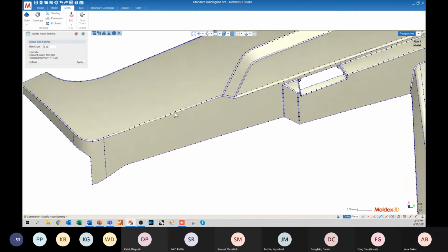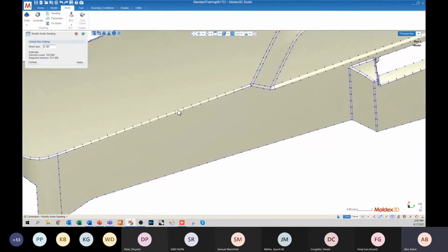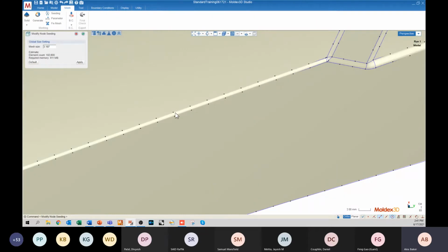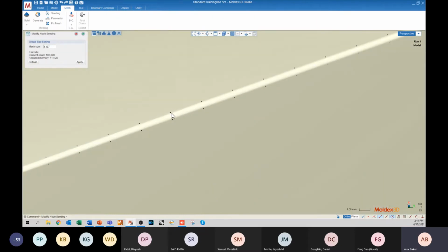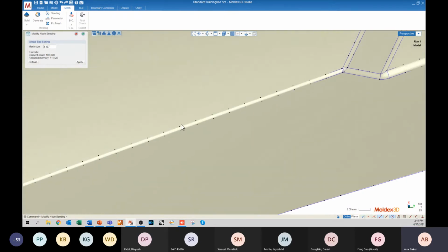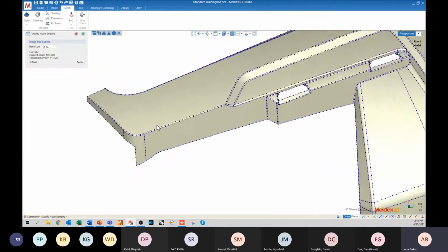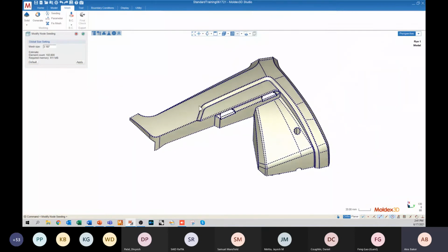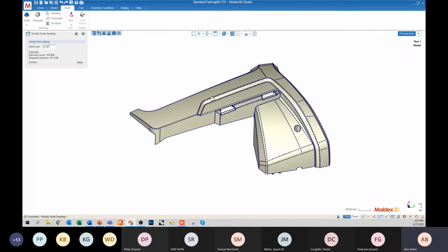All right, the spacing of these nodes dictates one side of the triangular element. So you could think of one element being this node and this node, right? So as I propagate that to the middle of my surface, you can see how these nodes really dictate the size of my surface mesh elements. And the size of my surface mesh elements are really going to control two main simulation trade-offs that we really need to take into account. All right, the first of which is computation time.